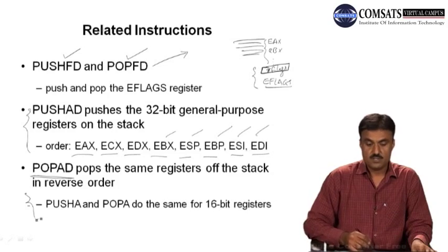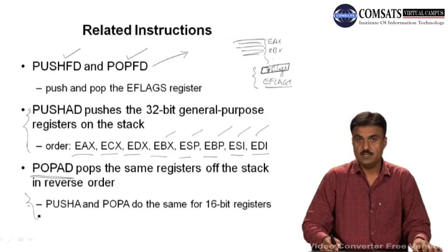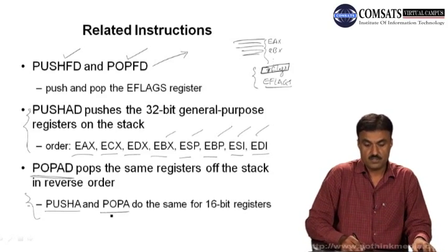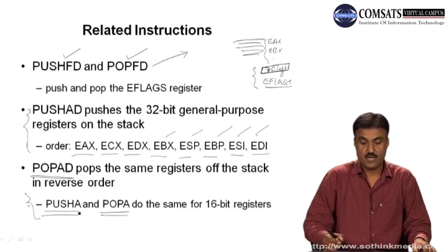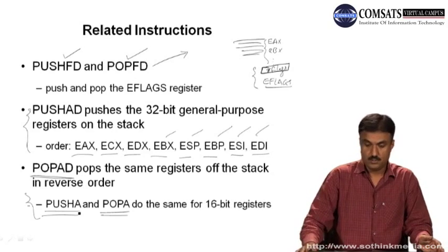Similarly, if we want to store all the 16-bit registers like AX, BX, CX, DX, SP, BP, SI, and DI, these are 16-bit registers. So if you want to store 16-bit registers, you have to use PUSHA and POPA. They have the same purpose.